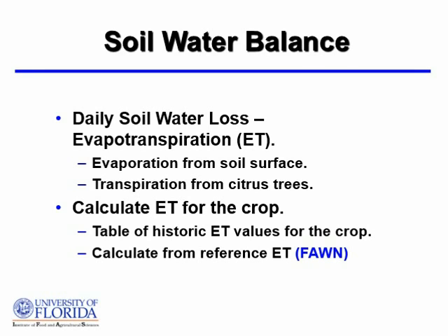They all work on a soil water balance method using daily soil water loss from evapotranspiration. And we talked about that earlier, how to calculate ET. We use weather data from FAWN to calculate the ET, and then we use the proper crop coefficients and soil factors in the models, as well as having soil type information for water holding capacities and things like that for the soils that you would enter into the program.